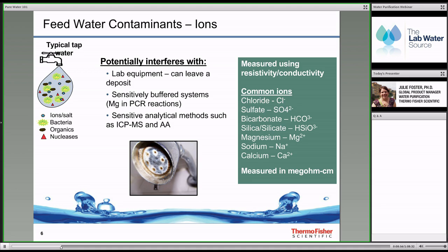You can taste hard water. It has a pretty distinctive taste, so a lot of homeowners install softeners in their basement or even RO systems, reverse osmosis systems, to remove the hard water. So that calcium and magnesium, even sodium, they all come from rock and soil areas that the water passes through before it gets to your home. And silica, again, another dissolved solid, it has a really weak ionic charge, so it's tough to get out of tap water, but that's also found in your water.